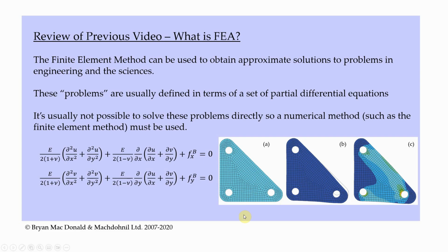So essentially, as we discussed the last day, the way the finite element method works is it still solves those partial differential equations on very simple shapes. So in this case, we've broken up the plate into lots of simple squares and quadrilaterals. We solve the partial differential equations for each of those little squares and quadrilaterals, and then we use some complicated mathematics to essentially glue all those answers together to give us an approximate answer for how it will displace due to the applied load, and again, an approximate answer for the stress or strain distribution in that plate as well.